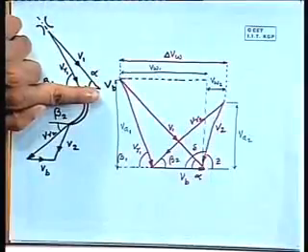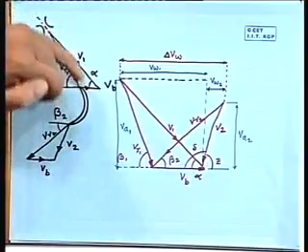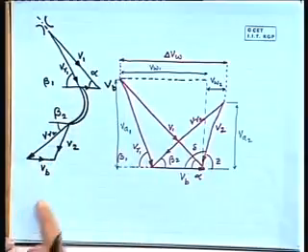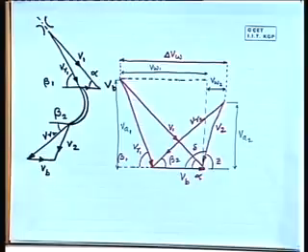Here steam is entering with a velocity v1, it will have a component in the tangential direction, this is the tangential direction. So, v1 into cos of alpha in this direction. Similarly, when it will go out, it will have a component in the tangential direction, and if we take the difference between them, then we will see what is the change in velocity along the tangential direction.